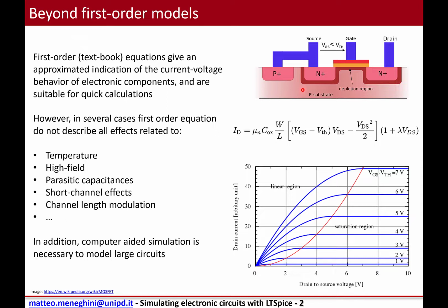Now, the point is that by using these relatively simple equations, we can reproduce the behavior of the circuits, but maybe we are not really able to describe all effects related to, for instance, temperatures, high field, parasitic capacitances that might be present in the device structure, short channel effects, channel length modulation, and so on and so forth. And in addition, in several cases, if we are dealing with very complex circuits, this study might require the use of suitable software.